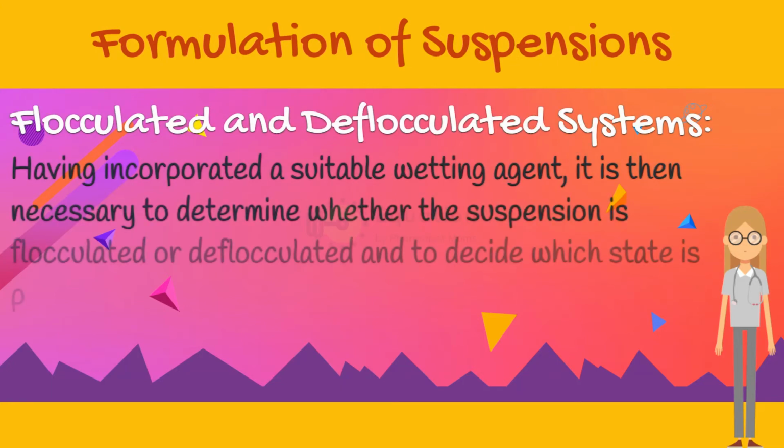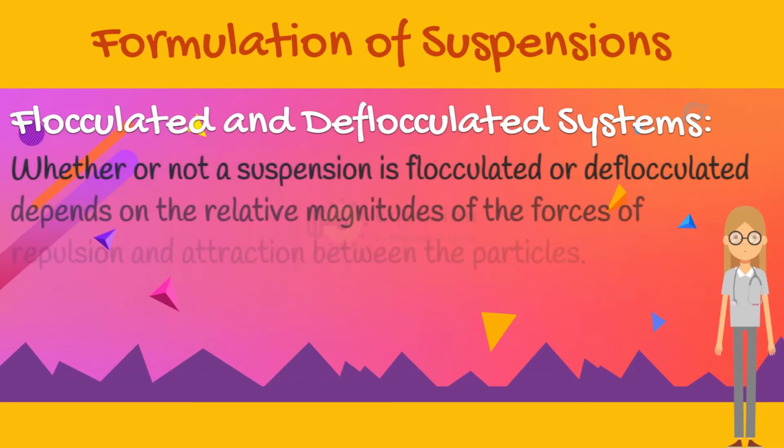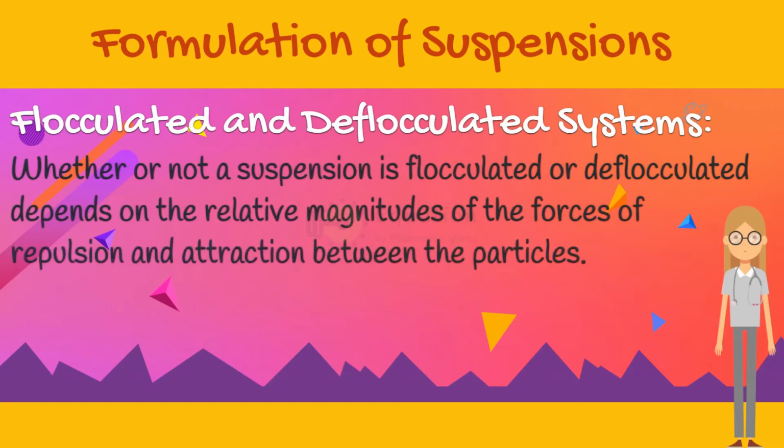Having incorporated a suitable wetting agent, it is then necessary to determine whether the suspension is flocculated or deflocculated, and to decide which state is preferable. Whether or not a suspension is flocculated or deflocculated depends on the relative magnitudes of the forces of repulsion and attraction between the particles.